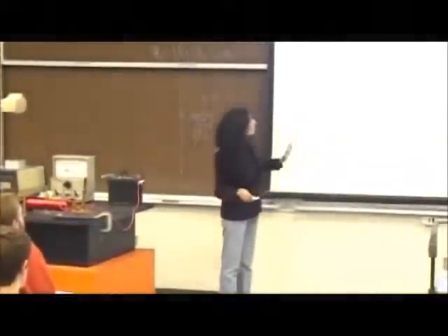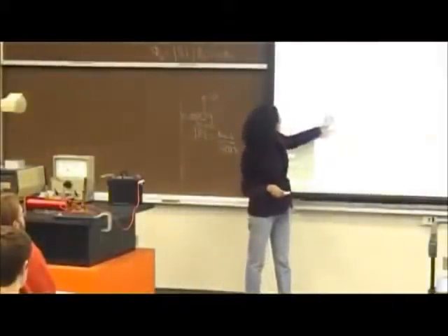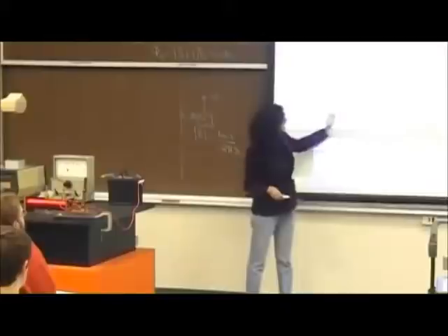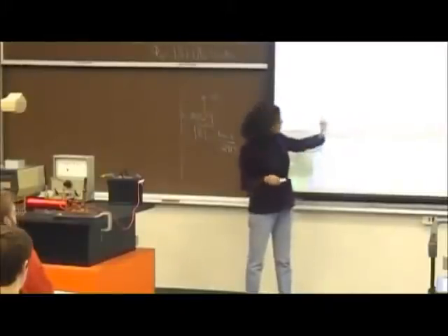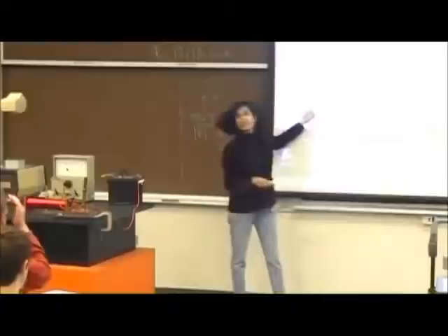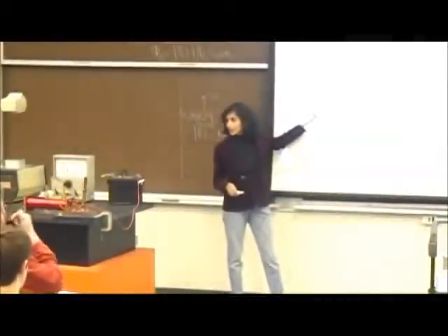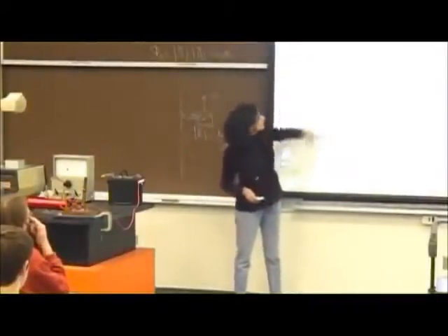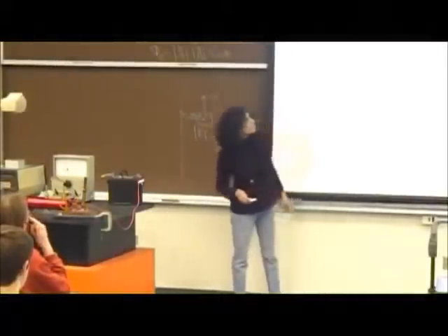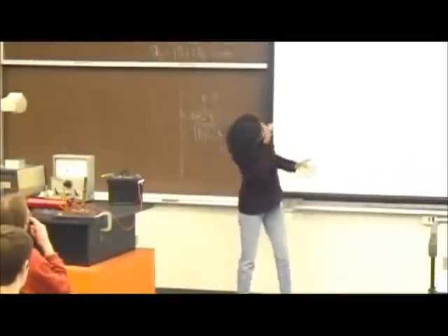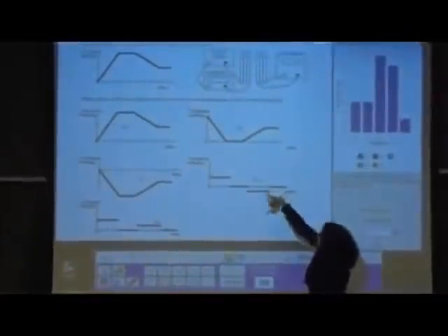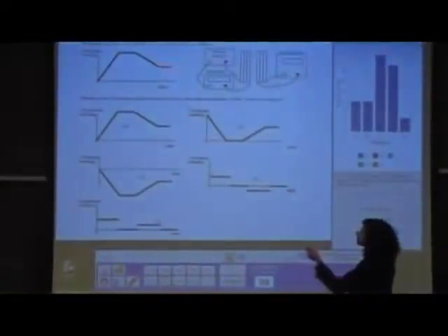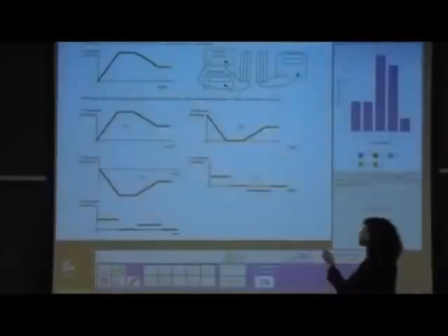So in other words, one thing we can see is here, for example, look, the EMF induced here or here are the same, sorry, what I mean is same in same direction. They are both positive, and that cannot be, right? Do you see? Because in one case the current is increasing, in the other case current is decreasing. So these two things should have been in opposite direction. Also notice, what about between these two cases? Should the EMF induced again go to 0 in this part? But here it doesn't. Do you see this is non-zero? So this is out too.